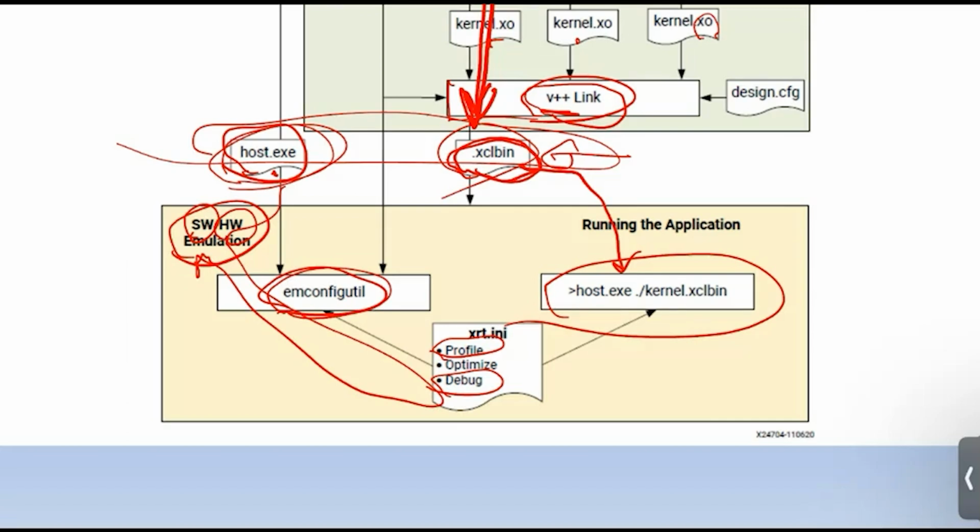The hardware emulation does not really reflect the actual system performance. Imagine you are doing the hardware emulation, and for this kernel function you actually run the Verilog simulation. So it is cycle accurate. Every cycle will exactly match the real hardware. However, another thing is different from running in the actual system. For example, the kernel function accesses the memory, but remember, in the whole system there are other processes also accessing the memory.